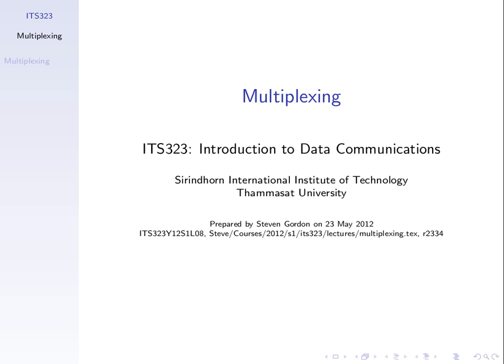And we send a signal representing all 1,000 phone calls to the exchange B, and that does demultiplexing and separates out that one received signal into the 1,000 individual lines. So this is our concept of multiplexing. Rather than having individual lines for each separate piece of data coming in, each separate voice call, use a single line and combine the data and transmit it as some signal across that single line. So that's multiplexing.